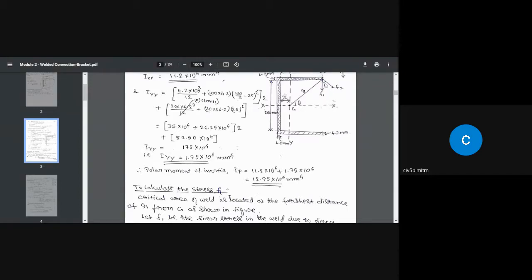Okay. So we need to find out what is theta. If we extend this line F1, this makes a right angle triangle. So we know this already. This is 90 degree, that is the angle between the line R and F2 is 90 degree. So this is theta, so this becomes automatically 90 minus theta. When you extend this line in this triangle, when this is 90 degree, this is 90 minus theta. This becomes 90 minus of 90 minus theta, that is equal to theta.